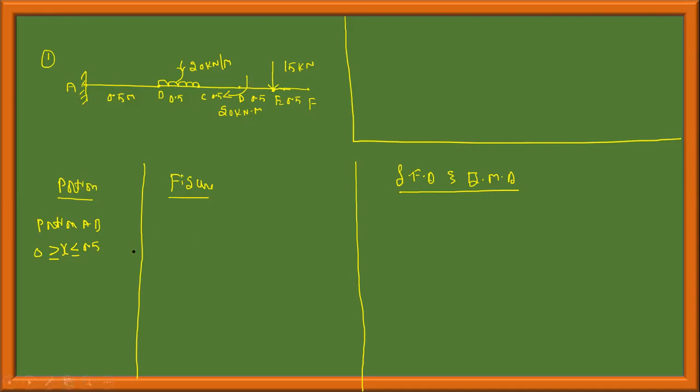Before that, I should find the reaction. Sorry, I forgot to write. Always you should find the reaction force. Without the reaction force, we should not solve directly like this. I will take reaction RA. I will take moment in any direction you want; finally, you will get the correct direction. I will take moment in anti-clockwise direction.